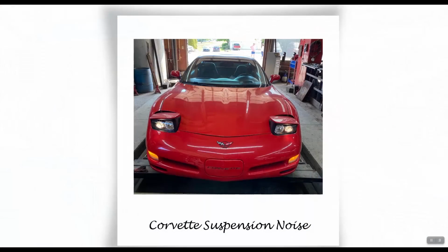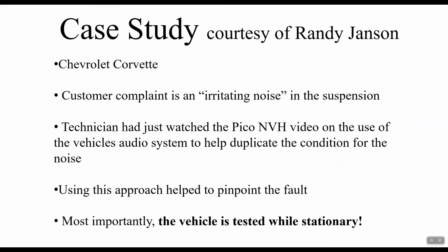Once again, thanks to Randy Jansen in the US for looking at this and sharing this. This is a Corvette with a suspension noise. Customer complaint: irritating noise in the suspension. The technician had watched the Pico NVH video, the previous one that we created on how to use the function generator. Using this approach, he managed to pinpoint the fault, and more importantly, the vehicle is tested while stationary. A valid point there is that there's no longer this repeat road testing.